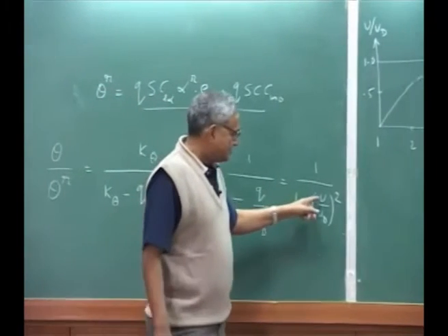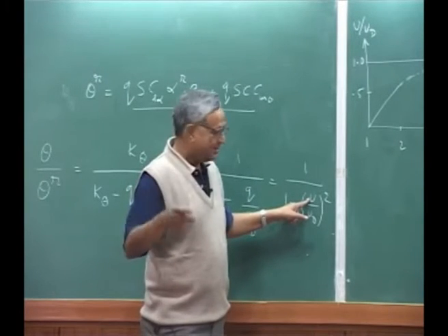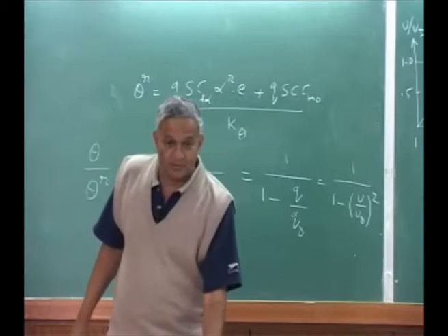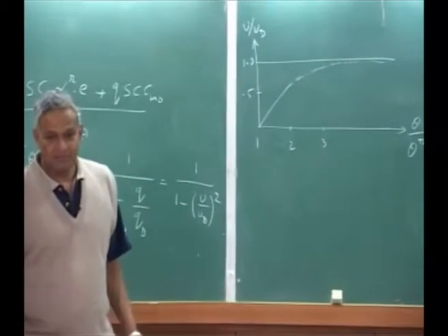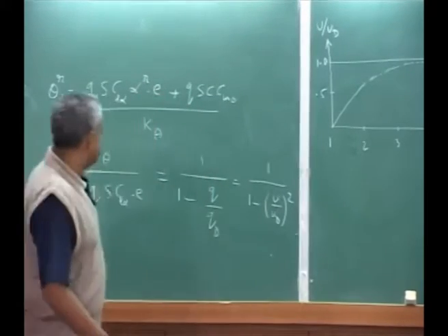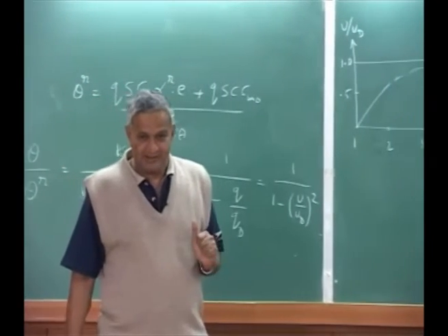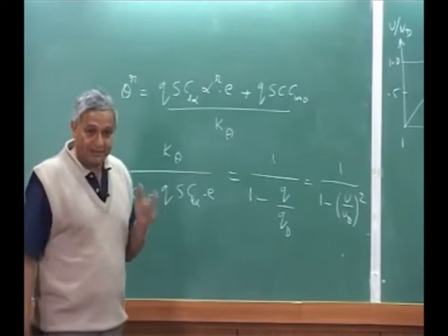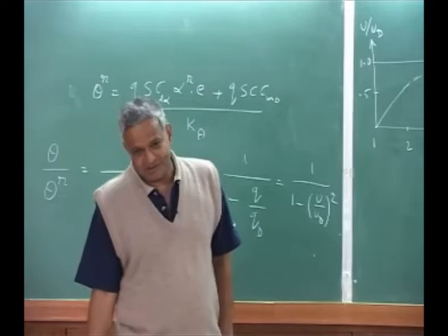Whereas if it goes to 60, 70, as you go higher, you will find that this is going to become very large. That means the error you make is going to be very large. Why is it necessary that you take this into account? It is not to calculate your divergence speed, because structurally you are twisting it more than what you predict by this assumption, which means the stresses which you calculate using this assumption will not be correct. You need to do an aeroelastic analysis to really predict the correct value of the stress. Then only you can design your structure.